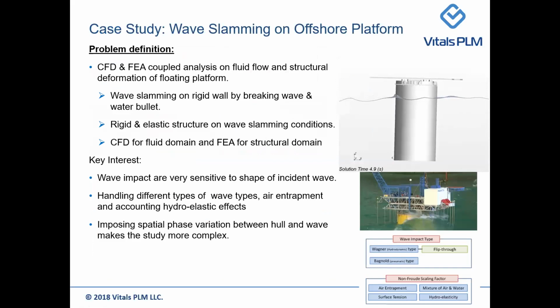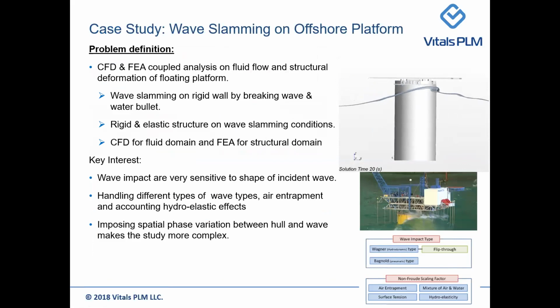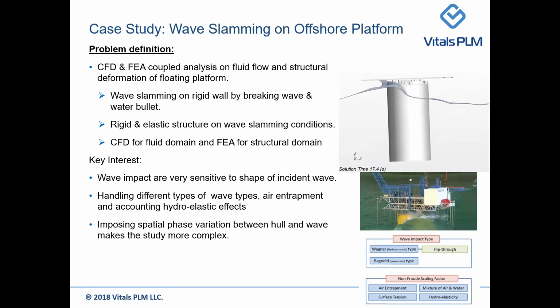Okay. Here I have a couple of case studies on FSI applications. Here you can see a fluid structure interaction, wave slamming on an offshore platform. Here is a CFD and FEA coupled analysis of fluid flow and structural deformation on a floating platform. A wave slamming on a rigid wall by breaking waves and water bullet. Here we studied the rigid and elastic structures during wave slamming conditions.